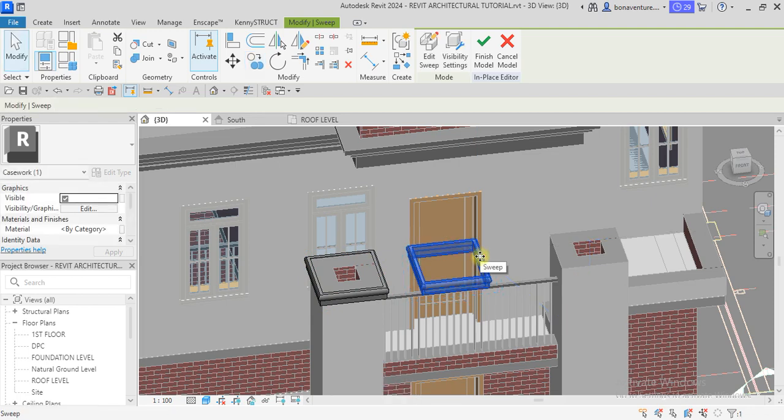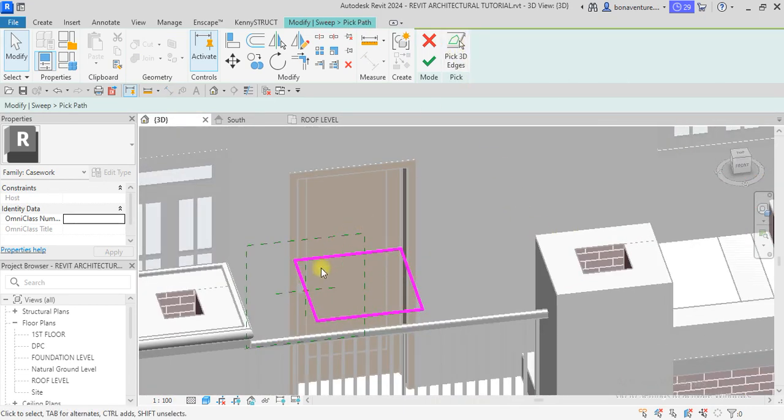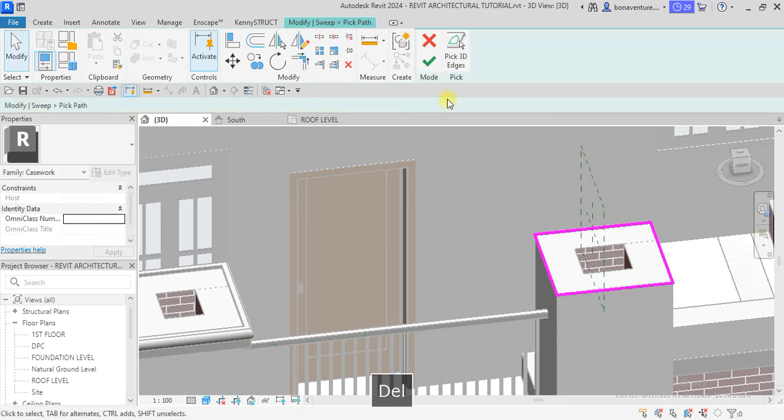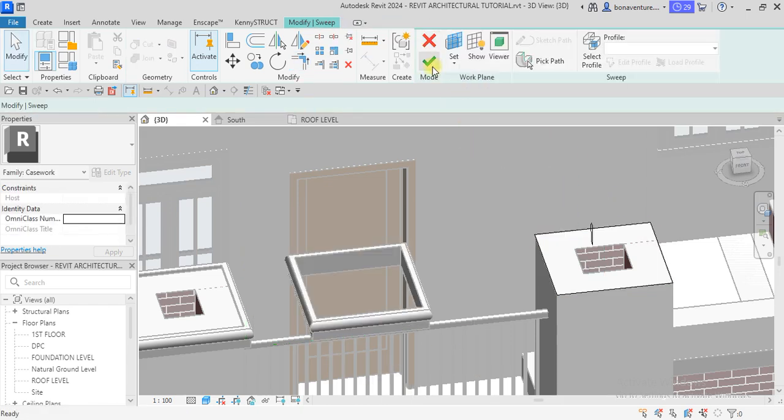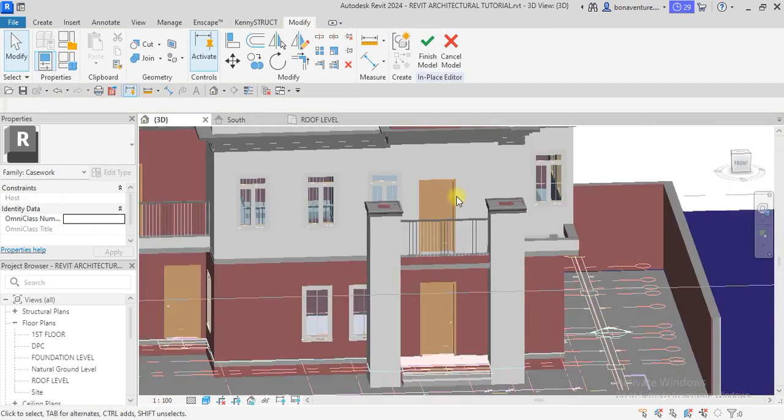Okay, let me click on edit parts, pick parts. So I will now transfer the part to this other side, pick edges. So I'll pick these edges. I'll say trim. So now I'll close up this and hit continue. Okay, so this is exactly what I want, right?